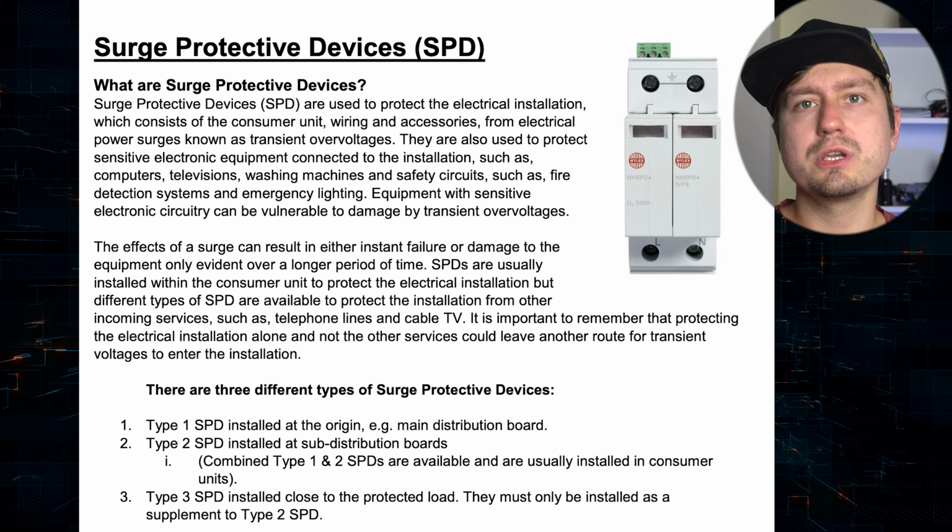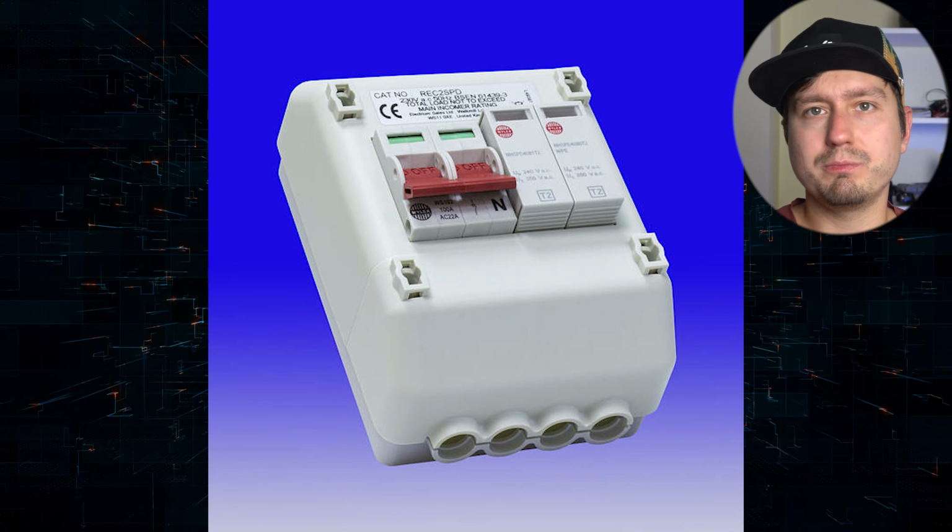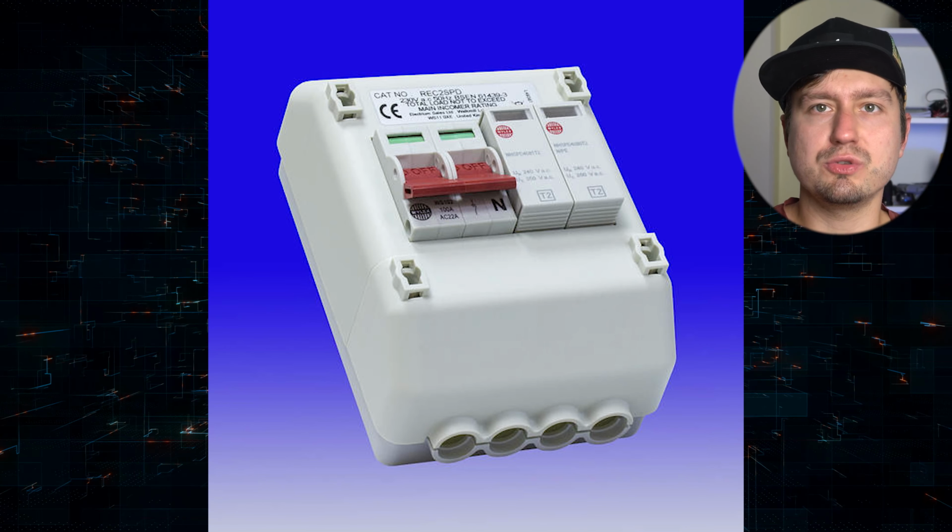So in that case, we really need to detect the overvoltage and switch off our device, and this is basically the best thing we can do unless we have a dedicated box with a dedicated heatsink for basically clamping this voltage to a suitable level.